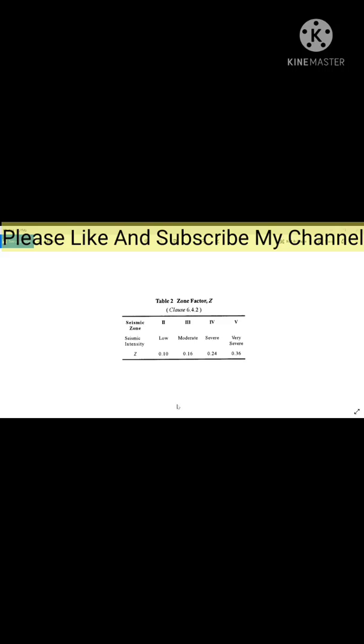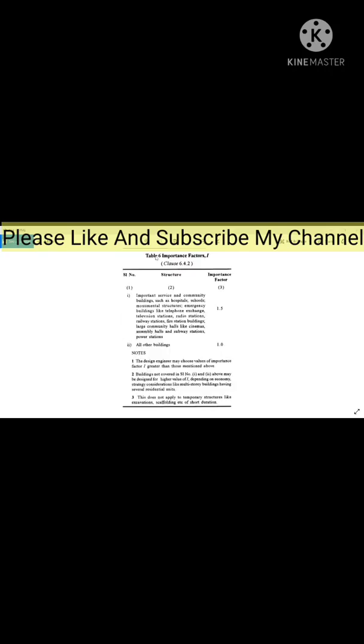Now we will go for the next factor, that is the importance factor. This is table number 6 given in the IS code, clause 6.4.2. You can read that clause. The importance factor depends upon the importance of the building. If your building is highly important, like community buildings such as hospitals, schools, monumental structures, then the importance factor will be 1.5.